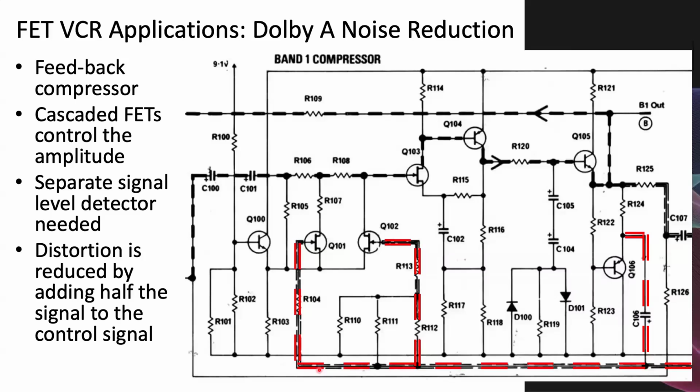to reduce the distortion. And again, the Dolby compressor is also a feedback compressor because of the nonlinear control of field effect transistors. You're pretty much committed to using a feedback style compressor to make them usefully work over a range of component values. In fact, these FETs had to be matched quite carefully.